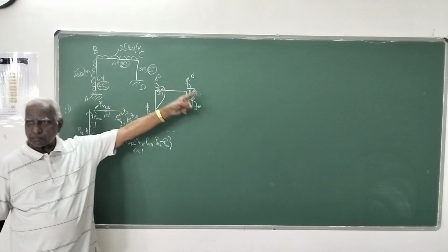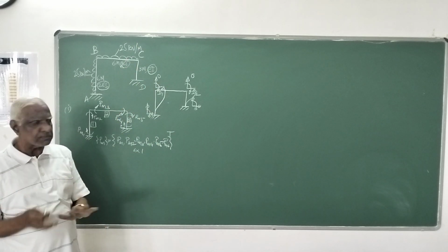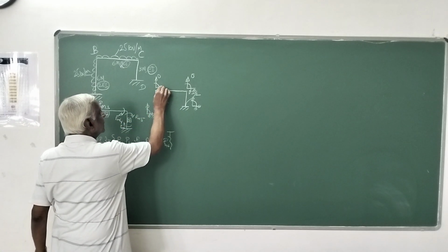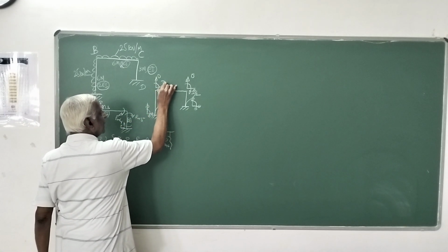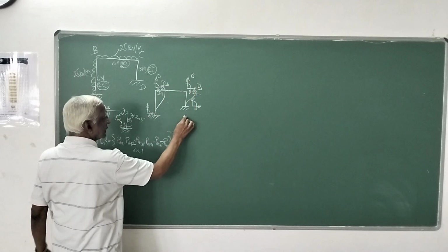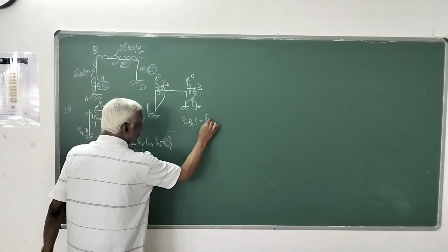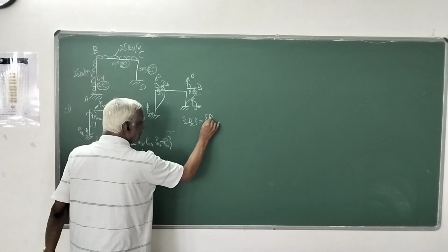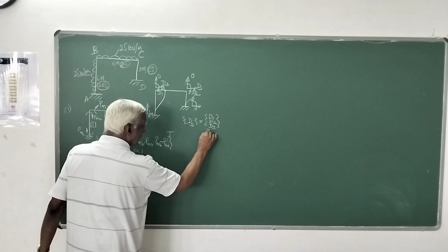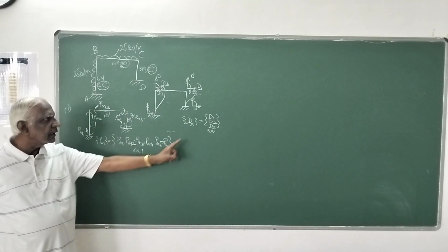So the unknown displacements, because of the given external possible displacements, are D1, D2 and this is D3 or delta, whatever it is, D3. So the ds is equal to D1, D2, D3. That is the 3 by 1 matrix. This is another thing we have to determine.